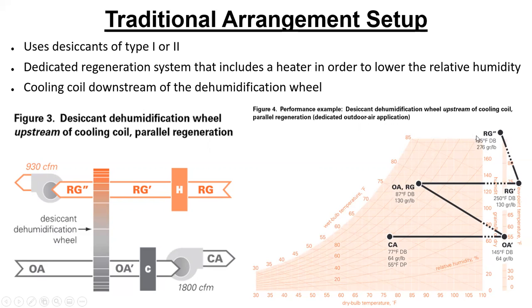And notice that it also cools down to 135. So we're dumping a bunch of heat into that desiccant. And so then that air is just discharged back out to the atmosphere, and all that moisture goes back outside, hopefully through a different location.